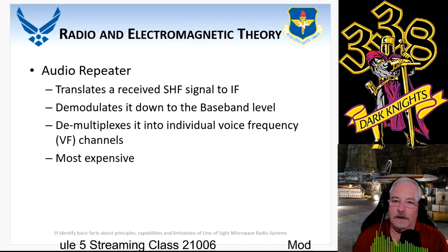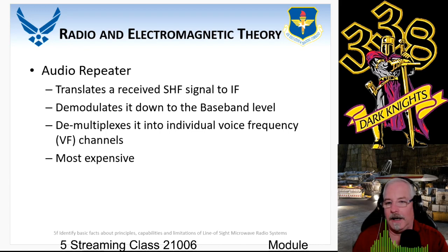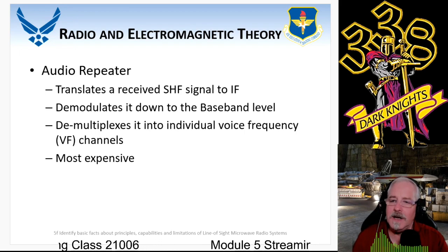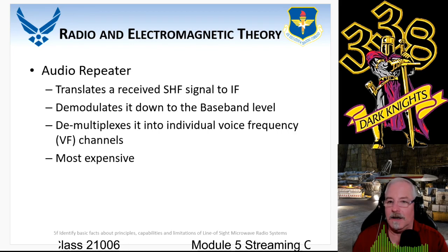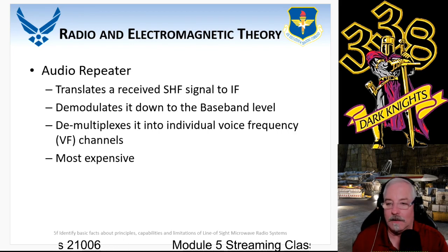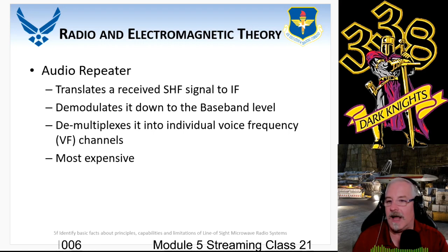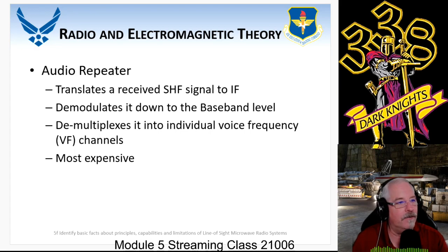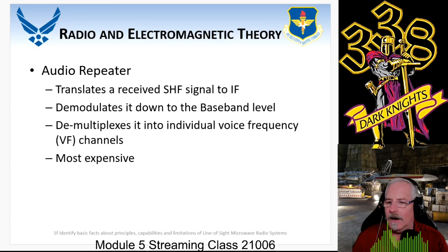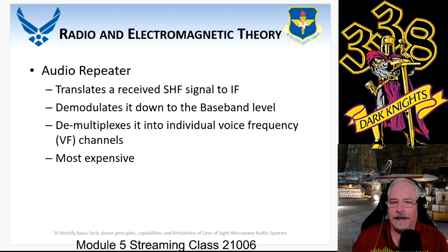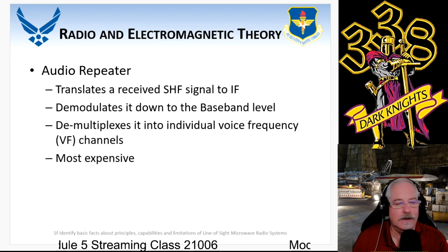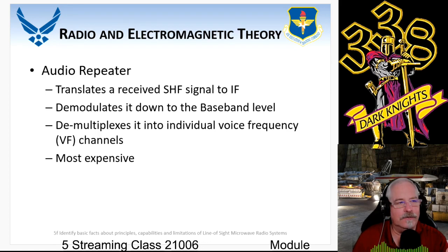We only touch upon the RF repeater and what is called PDM. So you have FDM, which is the RF, and PDM, which is actually the baseband. There is a difference between those two in how many repeaters you can use without the noise becoming a factor. I think RF is like 8, and with the baseband, PDM, you can break it down into 15.